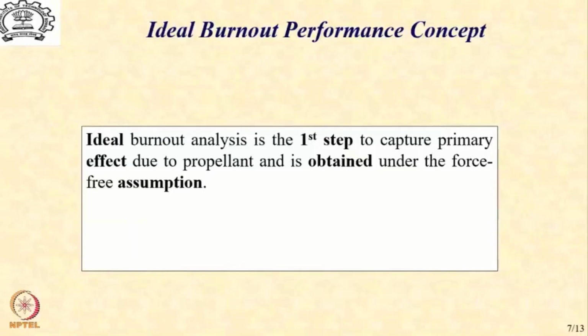We are going to burn a large amount of propellant. So obviously, we are going to generate large thrust, and thrust is definitely going to be the major force. So initially we can say that apart from thrust, there is no other force present, or what is called the force-free assumption.